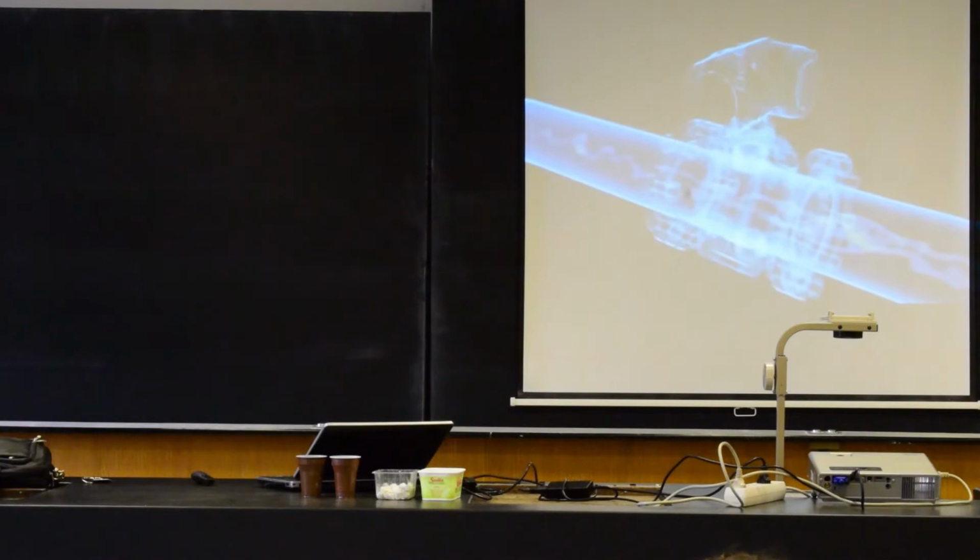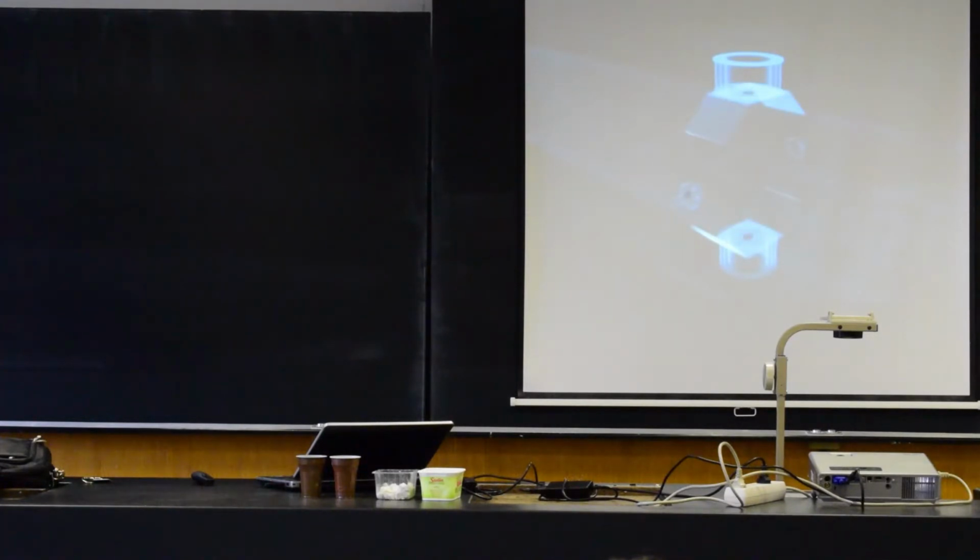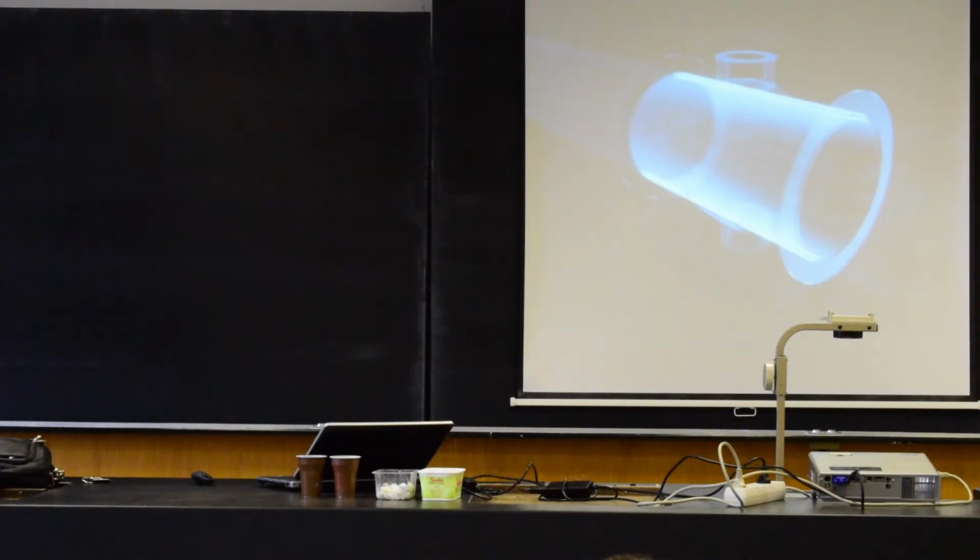Let's take a closer look at how this measurement method works. Two field coils are located inside each electromagnetic flow meter. With the help of what are termed pole shoes, these coils generate a constant magnetic field over the entire cross-section of the measuring tube. Two electrodes, which can pick up electrical voltages, are installed at a right angle in the wall of the tube. The lining fitted on the inside wall prevents electrical short circuits between the conductive liquid and the metallic tube.